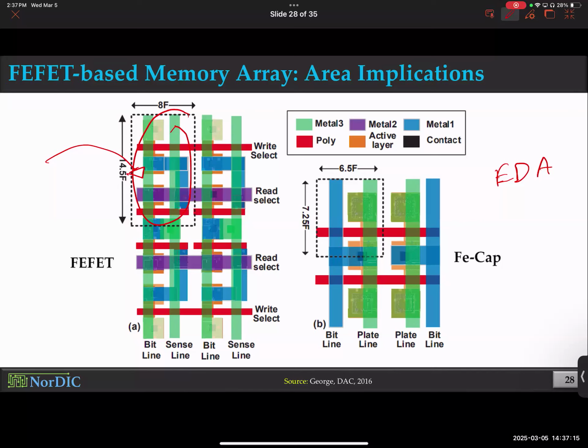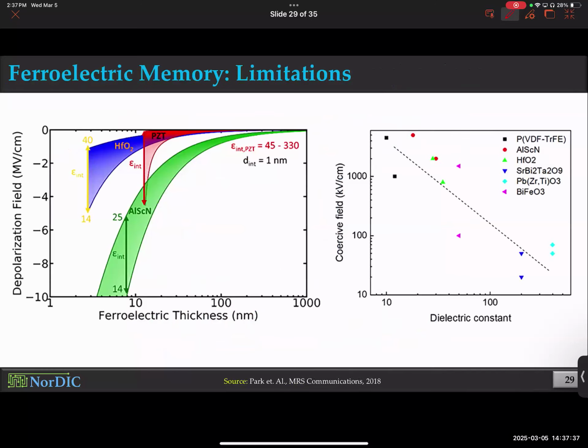So when you see this 1T1R cell being emphasized so much, where's the circuit? This is the circuit, basically, right? Just take it, copy it over, you get an array. So going from device to array is like this for memory design, for the most part. Device to array. I didn't say peripheral. Okay, peripheral is a very different beast. We'll talk about that.